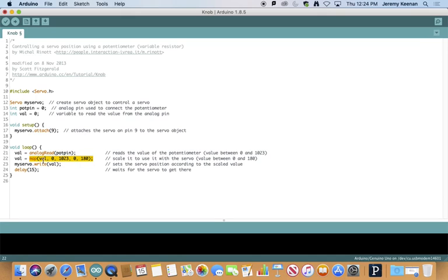But what's happening here is we have a value, which again is the output of this analog read function. We've plugged it in here. We're saying, okay, val, now I want you to equal the result of this map function. So it first puts inside of val the analog read right here, and then directly after that, it puts inside of the val variable the output of this map function. So the map function is returning a particular value that we are then storing briefly and temporarily in the val variable.